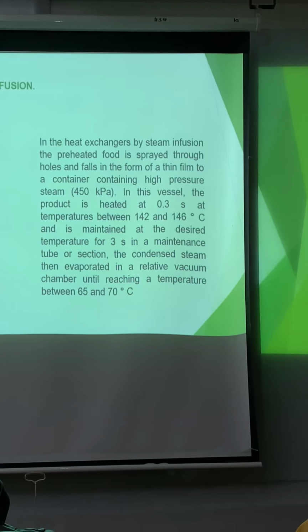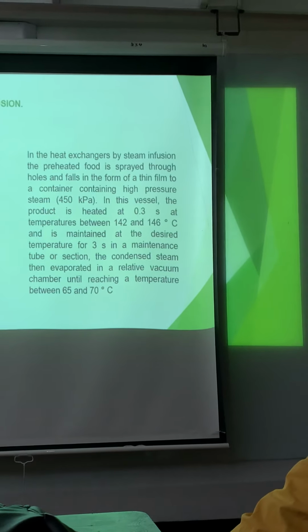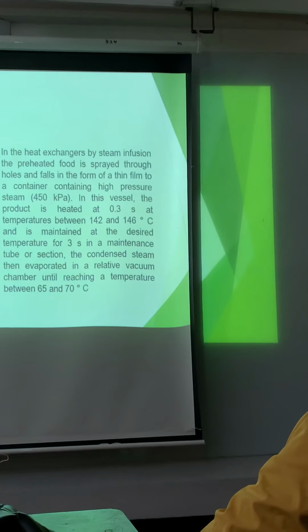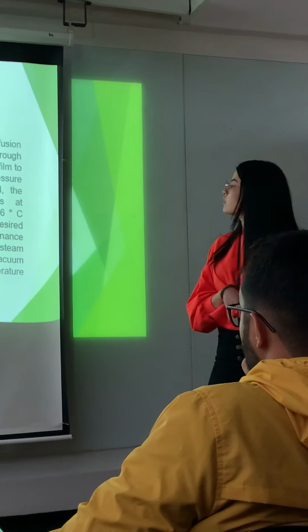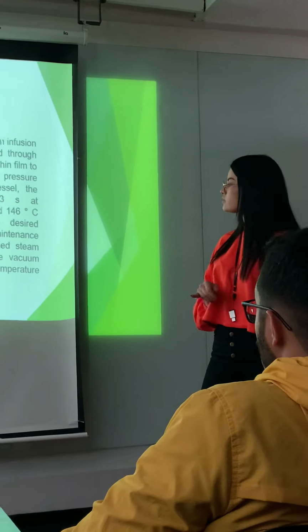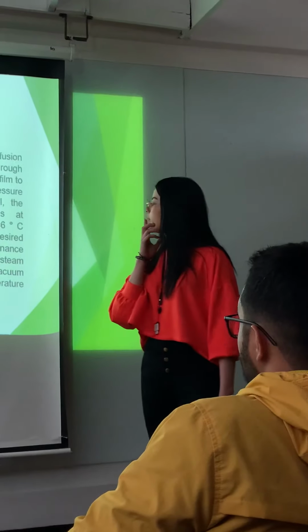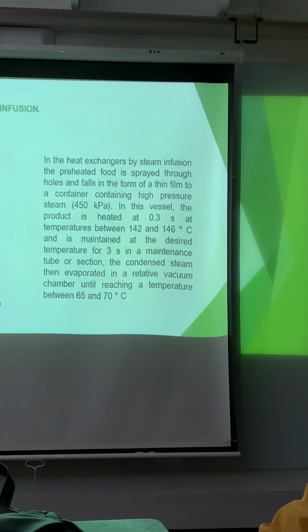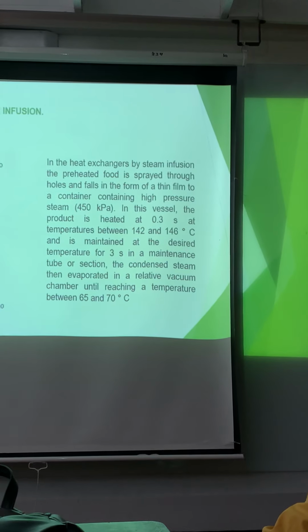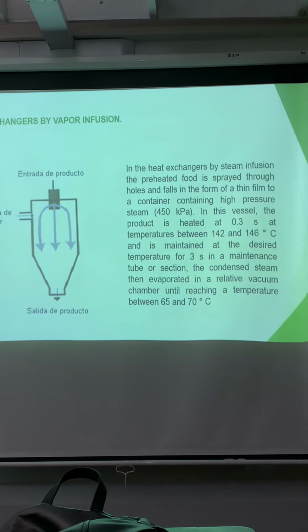to a temperature between 152 and 156 Celsius and is maintained at the desired temperature for 3 seconds in a maintenance tube or section. The condensate stream then evaporates in a relative vacuum chamber until reaching a temperature between 65 and 70 Celsius.